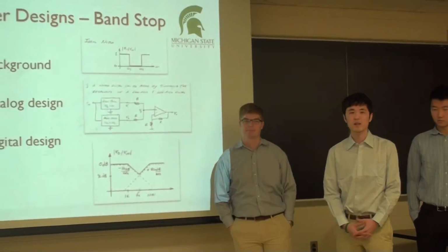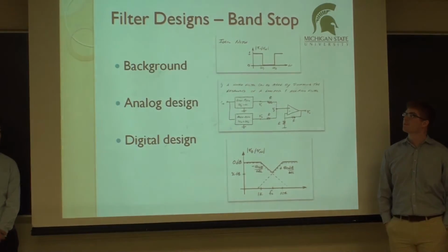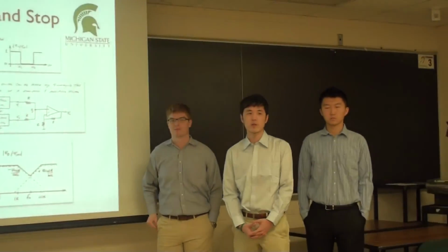Next, I'm going to talk about the bandstop filter. A bandstop filter passes most frequencies, but it attenuates a specific range of frequencies to very low levels. A notch filter is a bandstop filter with a very narrow stop band, which means it has a very high Q factor.